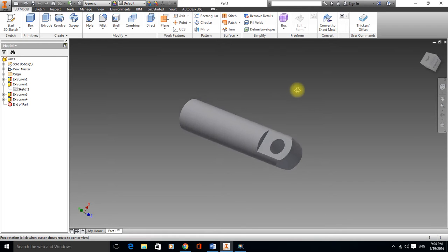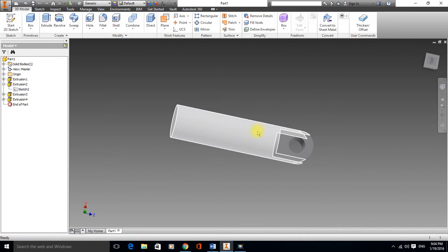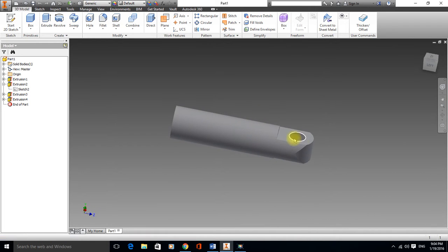Or you could hold the component horizontally in a vise like this, and you could use the end of an end mill to actually machine this face, flip it over, machine the other face, and then put the hole through. Both ways there would be two different operations. One way might be better than another.